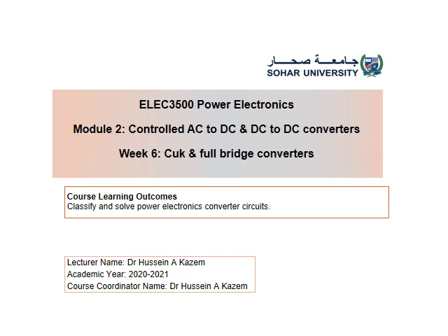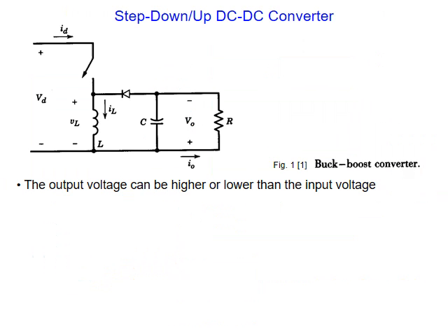We are going to discuss the Cuk and full bridge buck-boost converter. How does this circuit work? You see, when I switch on here, this diode will be open circuit and the current flows through the inductance and stores energy. When I open it, the energy is released through the diode, which will conduct, and we have here